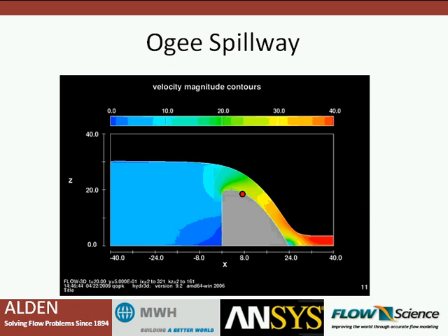So right where the highlighter is here, the underside of the nappe that you would get if it was just a sharp crested weir. So during the design flow, since the shape of the spillway is supposed to follow the underside of the nappe, you would expect the pressures on the surface of the spillway to be just about 0, and that's at the design flow.